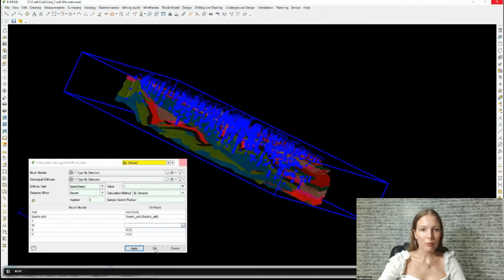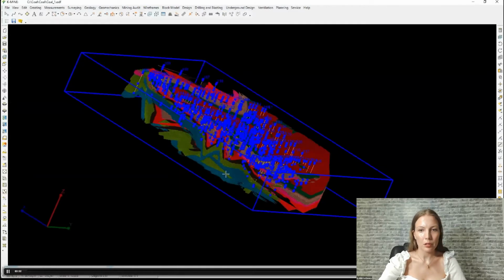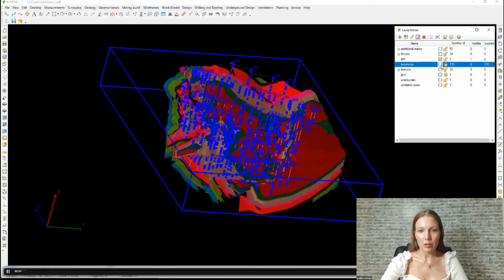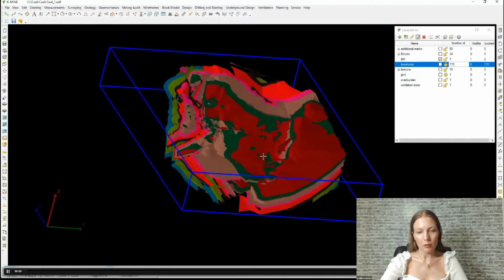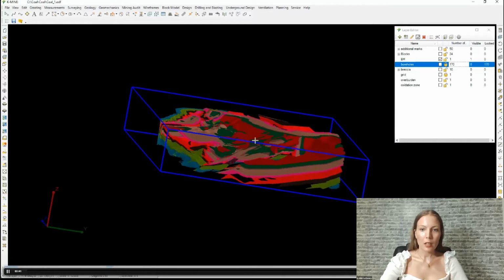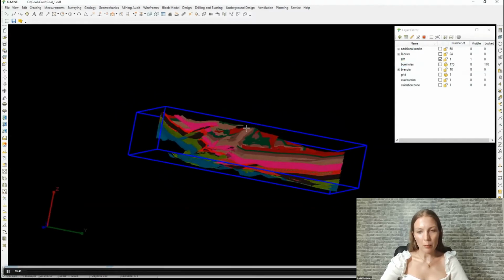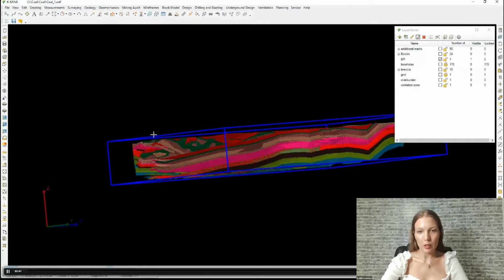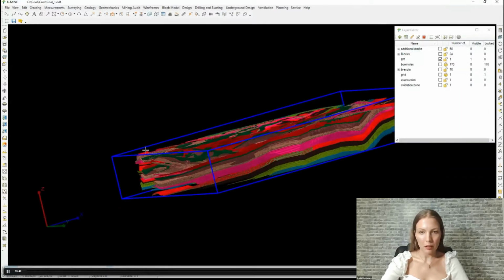So now we set visible only coal seams and calculate block grades and volume. And again, you can also recalculate reserves and resources if you plan with quality requirement parameters, and if you're changing minimum seam thickness, maximum permissible dead rock thickness, ash content, plastic property, or weathering depth.